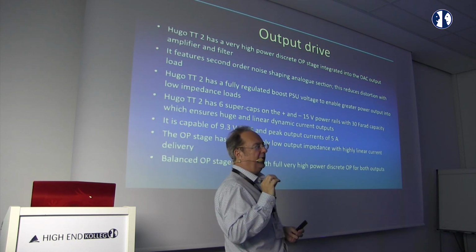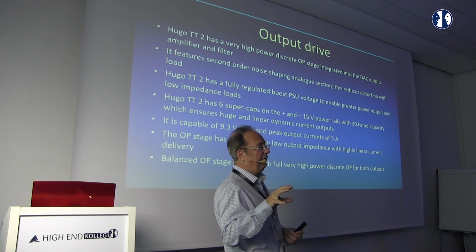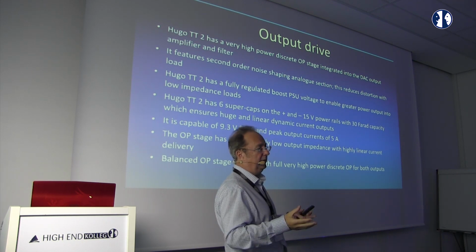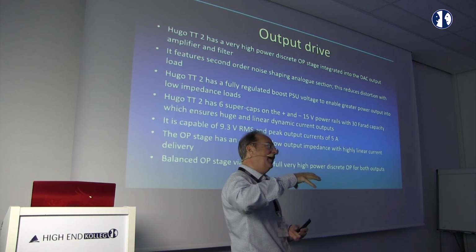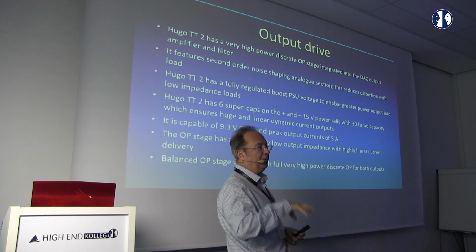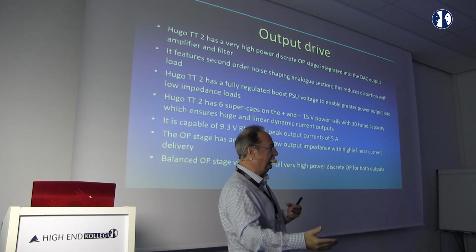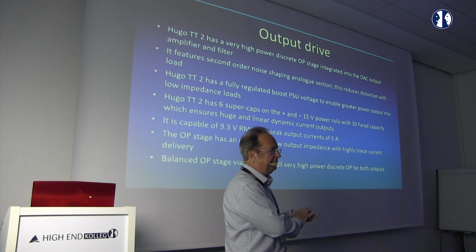The other benefit is that the noise shaper runs at 104 megahertz. That's an extraordinarily high rate. Normally noise shapers run at 3 megahertz or 6 megahertz at a maximum. That means that my filtering characteristics can be very simple. Simple filter characteristics means a simple number of components. Simple number of components means better depth perception, better detail resolution, lower noise floor modulation.